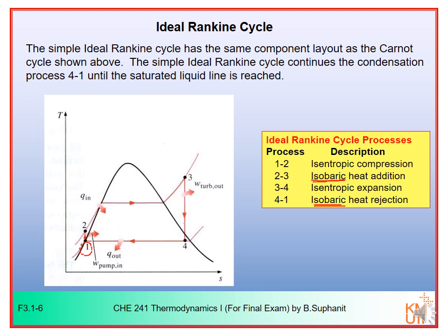And if I say ideal Rankine cycle, it means that number 1 would have to be sat liquid. Sat liquid here. Okay. So the first process would be process 1, 2. Start by pumping the sat liquid, okay, to a higher pressure. So we have two pressures here, P high and P low.